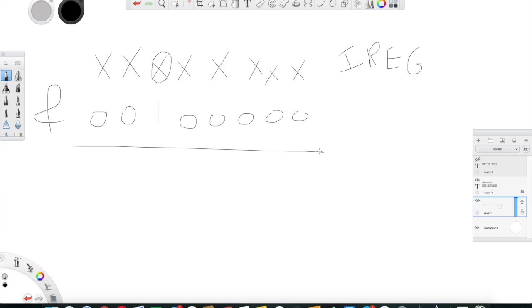Okay, and then here I will have what? 0, 0, X, 0, 0, 0, 0, and 0. So actually I wanted to isolate bit number 5 from the remaining bits, or the rest of the bits. So what did I do? I performed an AND mask. I cleared all the other bits, and I ANDed my intended bit number 5 with 1, so I can have its value.